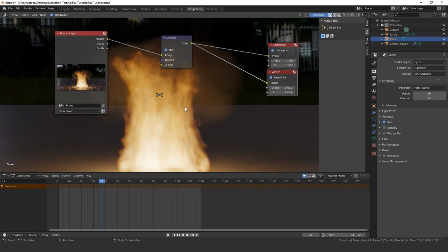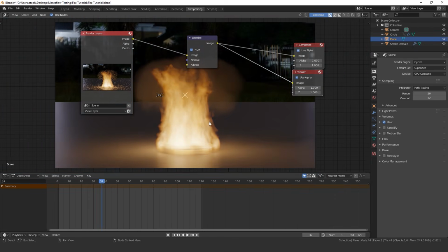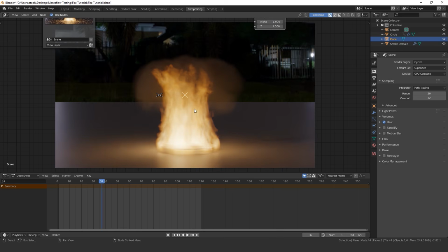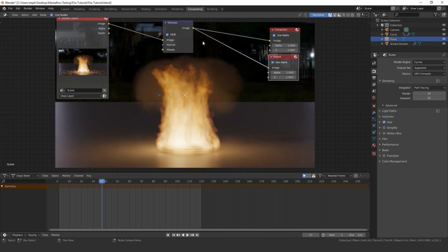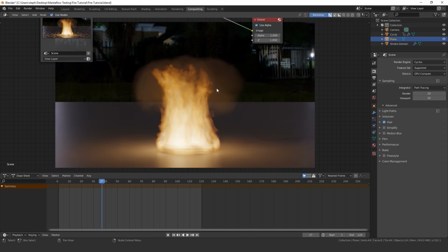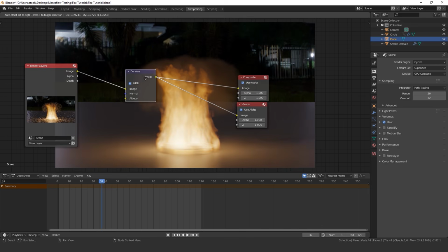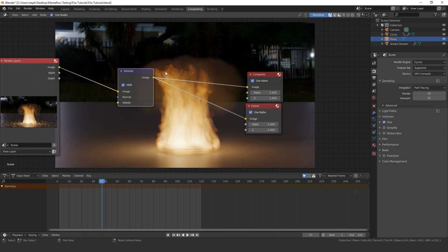And once this loads, we can see, I'll press V a couple times, you can see all of the noise is gone. Just like that. With just a simple Denoise node, all of it is now gone, and this is what our image looks like. Now with this Denoise node in place, we are ready to do a full animation.